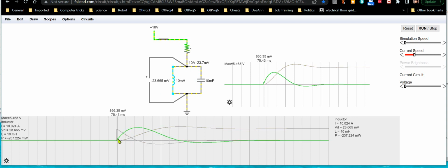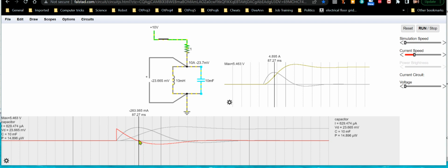You see the voltage isn't zero, and it's not 100%, but when it's in this intermediate state, the capacitor is actually charging up at first. And that's what you see. At first it's got a really high current, almost 10 amps. But it's decreasing as the voltage across the capacitor increases. And when its current hits zero, which is right about here, that's at peak voltage.